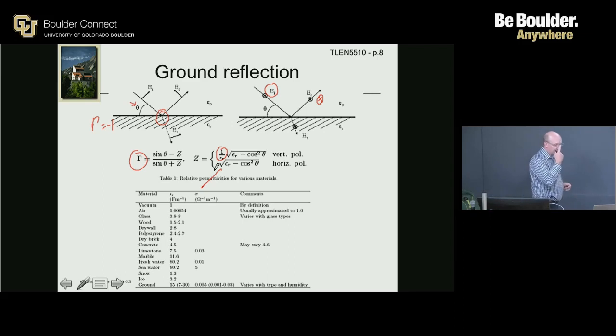Sigma here is not a normal standard deviation like we'll see in most of the rest of the class. Sigma here is the conductivity in Siemens per meter, or in 1/ohm per meter. But it's generally not very significant unless you talk over seawater. If you deal with communication over water, it becomes important. Otherwise, you'll see in homework, you'll have to do different things. If you vary epsilon r from those various things, the general picture will not change that much.